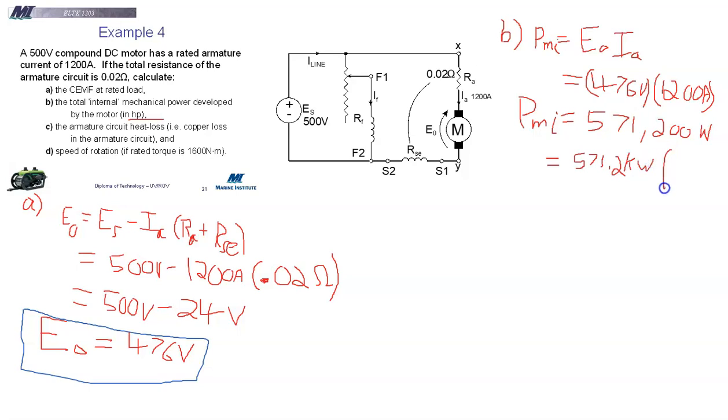And we're going to multiply that now by 1 horsepower over 746 watts. And if we want it to cancel with kilowatts, we'll use 0.746, that should be a 4, and so 746 watts per horsepower, right? And so 0.746, and the unit in there that should be in there is a kilowatt.